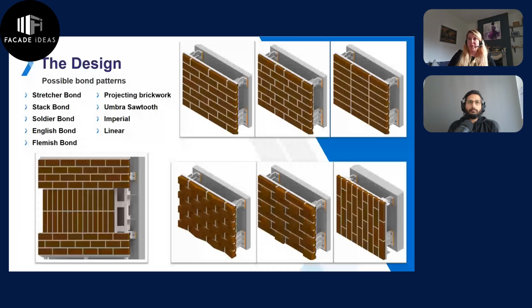We've got an example of Flemish bond there, which utilises both the stretchers and the headers that I showed you earlier. Stack bonded as well, very useful if you want to specify a project or a building that has a lot of stack bonded elements. A brick-faced cladding system is particularly useful. If you were going to build that traditionally, you would need to use bed joint reinforcement. You may need extra wall ties because there's no triangulation of the loading. It's a very weak structure. So we would need those extra ancillary items to be specified to ensure that the wall was maintained.